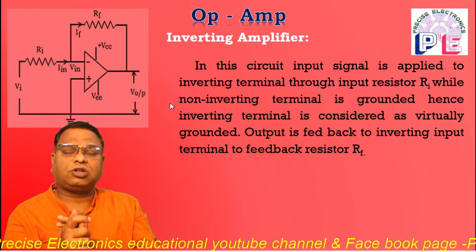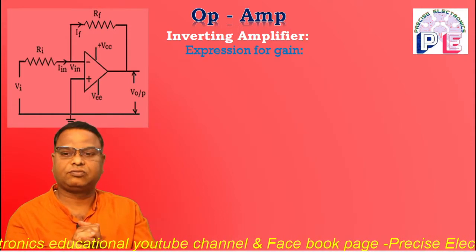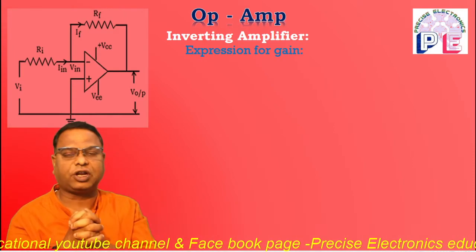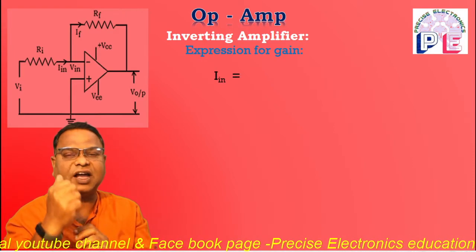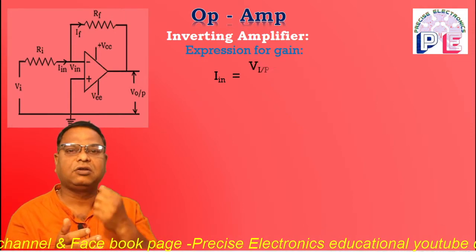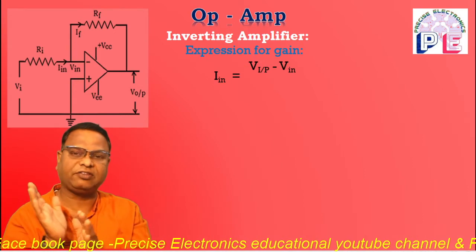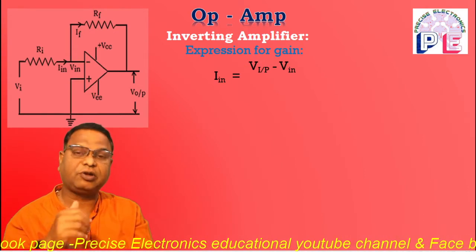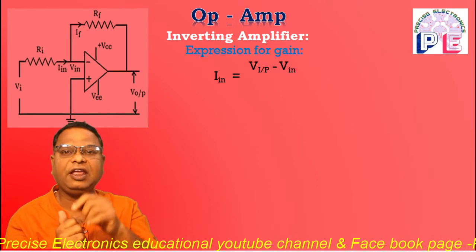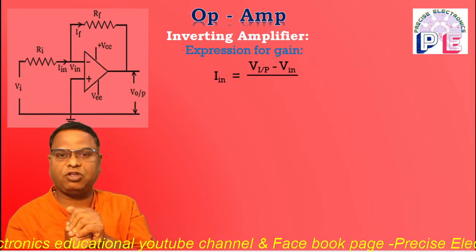Now we have to find out the expression for the gain, how the gain is calculated. First of all, we have to find out the current flowing through input terminal, and that is considered as Ii. So what is Ii? Ii is given by using Ohm's law. So Ii is equal to Vi, that is the input applied to the inverting terminal through input resistor Ri, minus Vin. What is Vin?